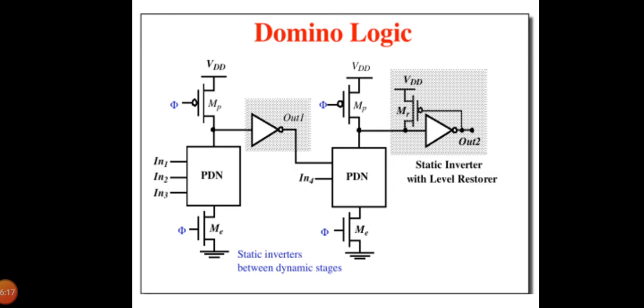Using differential domino, it is possible to implement any arbitrary function. This comes at the expense of increased power dissipation since a transition is guaranteed every single clock cycle regardless of the input values. Either 0 or 0 bar must make a 0 to 1 transition.